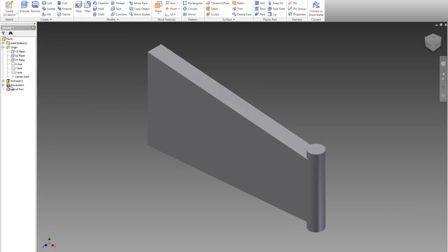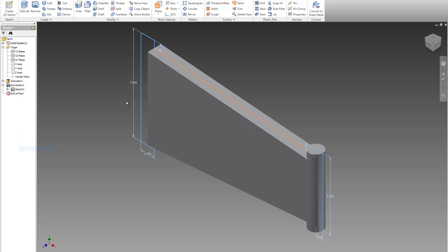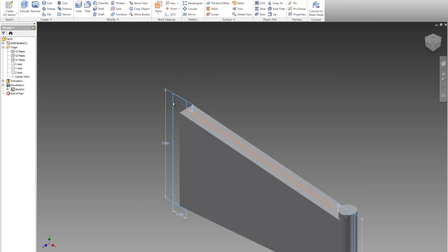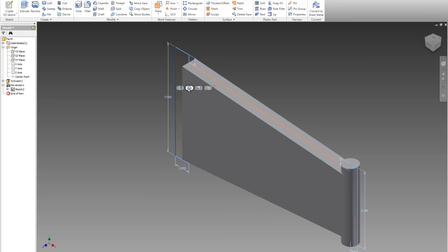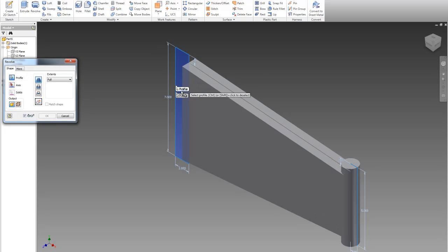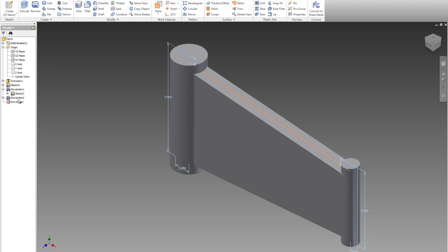Now again, I was saying I can reuse that sketch, so I simply just go up into my model tree, turn back on that visibility, and I can continue on with my design. Again, by selecting a line, you're going to see those new glyphs appear. These are different options that are common based off that sketch. Simply just selecting my axis, and with that green check mark, that allows me to close out of that box.